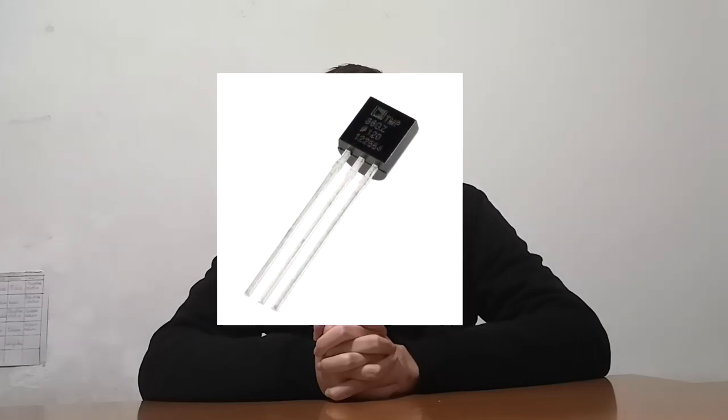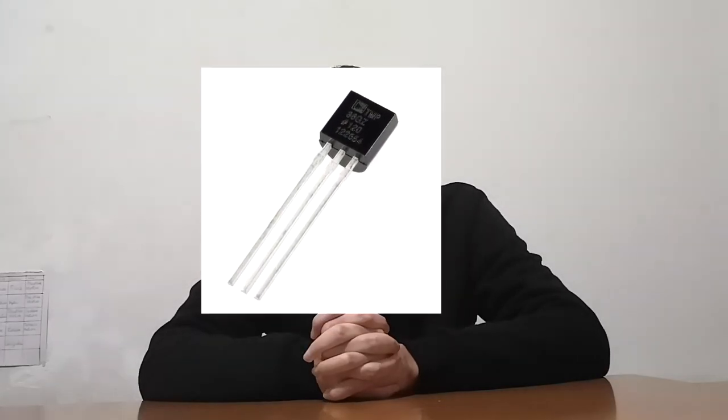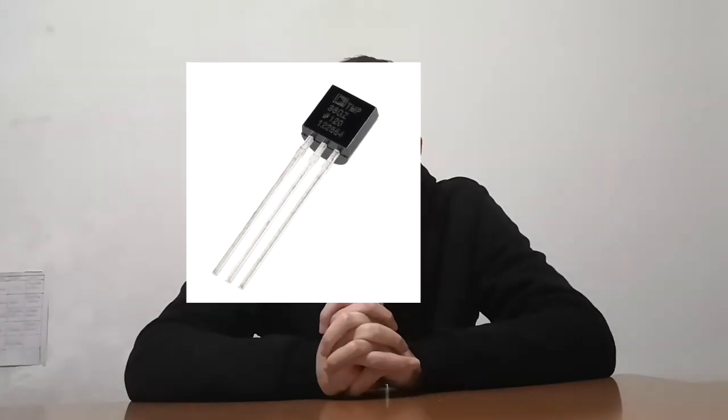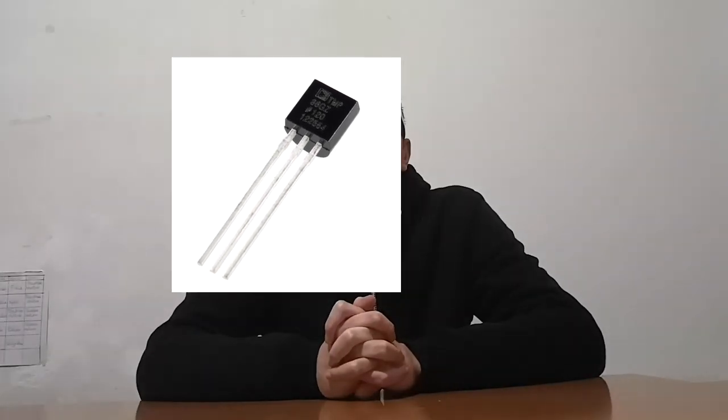Hi everyone, today I will talk to you about how to make a temperature and a gas detector with Arduino. To be able to do this, first of all we need the TMP36, the analog temperature sensor. It provides a linear analog output directly proportional to the temperature expressed in degrees centigrade, and that is why we interface it with Arduino through one of the analog ports.